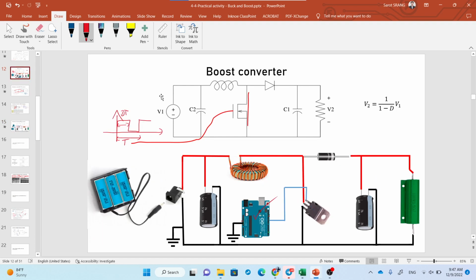So you're going to check the actual device just to see some important signals. For example, the signal sent from the microcontroller to the FET, and you also observe the output signal from the FET here. So first you observe this signal, this one with respect to ground.